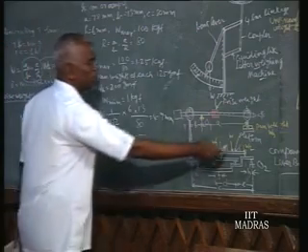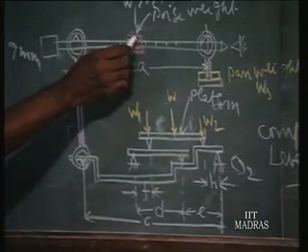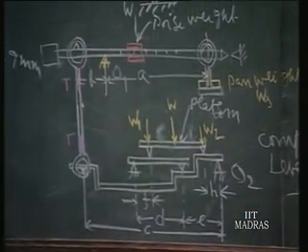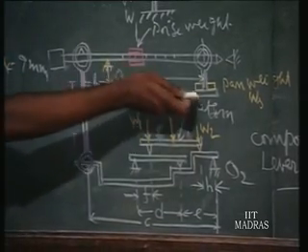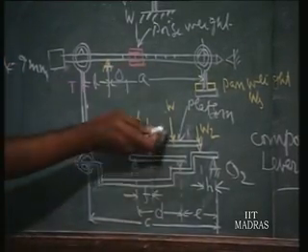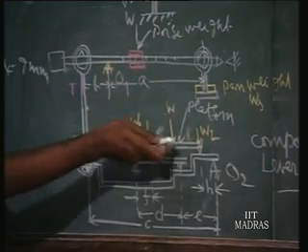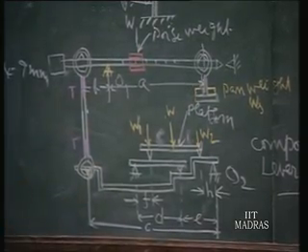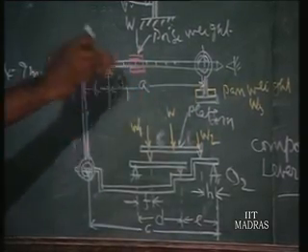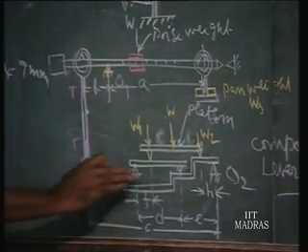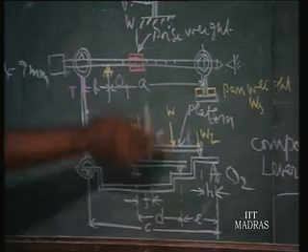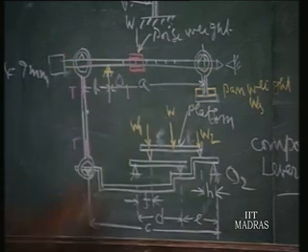So that is the pan weight. But how is the poise weight decided, and how is it made use of? Normally a pan weight is added for every 100 kilograms. Suppose the range is 1000. For every 100 kilogram weight we add one pan weight, and in between, say 100 to 200, we move the poise weight. That is how the measurement is made using this compound balance. Between the pan weights, to the extent the weight is there, we move the poise weight.